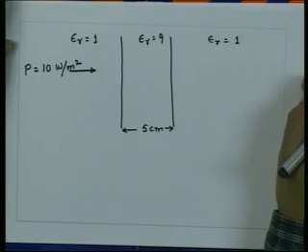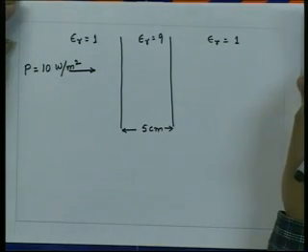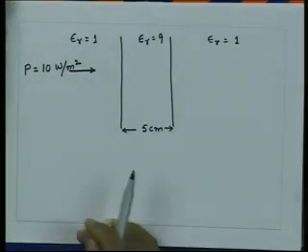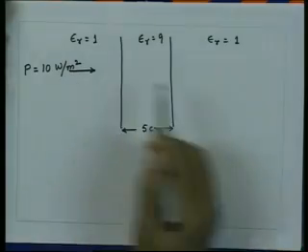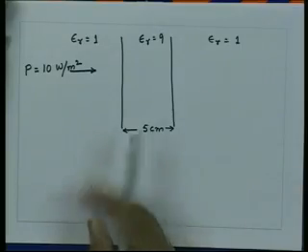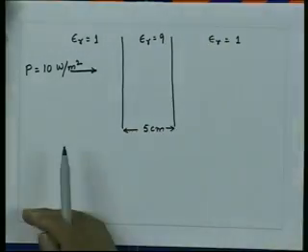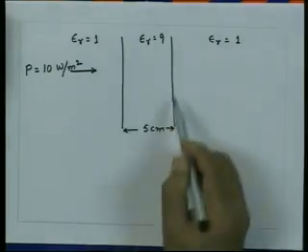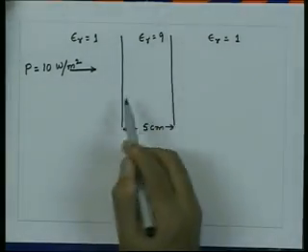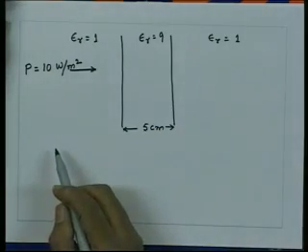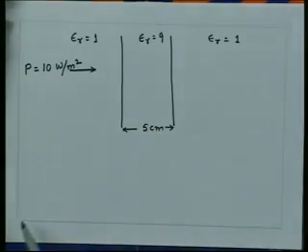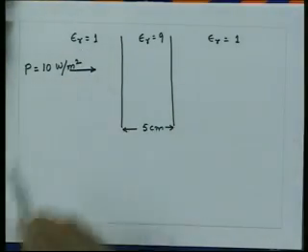This problem essentially can be solved in many ways. One is, since this is a normal incidence, we can treat it like a one dimensional problem. So, we can treat it as if you are having a medium here which has a certain impedance. So, it is like a long transmission line. Then you are having another section here whose medium parameter is this. So, it has a different characteristic impedance, and then on this side again you are having an infinite medium. So, you have another line which has an impedance which corresponds to epsilon r equal to 1.